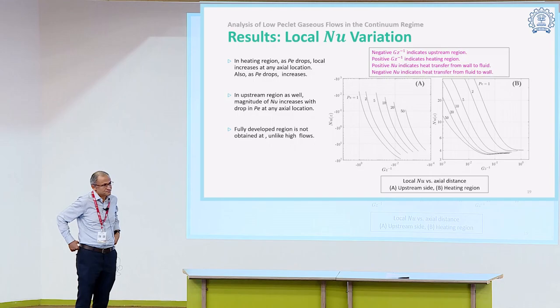I didn't see the wall temperature measurement simultaneously, because you showed the centerline. Did you show the wall temperature? We have only centerline temperature measurements. Initially, when we were doing these measurements of overall heat transfer coefficient, we were finding that the wall temperature is essentially not changing. But we have never really measured the wall temperature. One can do it in the simulations, where we can see how exactly the temperature is varying, and that I had shown.